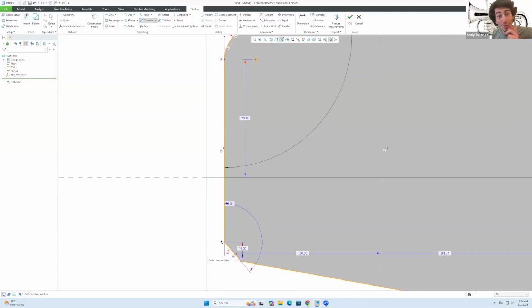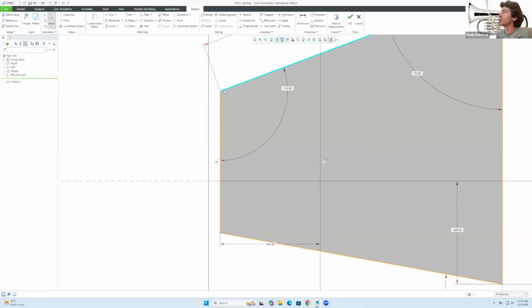Great tools. However, these are the last two times that I'm going to use chamfer and fillet within a sketch. These are two things that you could do afterwards once you have a 3D volume. I'd rather keep the sketch simpler and then add details like the chamfers, the fillets, like these rounded edges later on. I think it's a strategy that has always worked. So I'm going to get rid of those, especially because it modifies the sketch properties, and sometimes I want to modify the radius. It's easier to modify later if the chamfer and the fillet are features themselves.